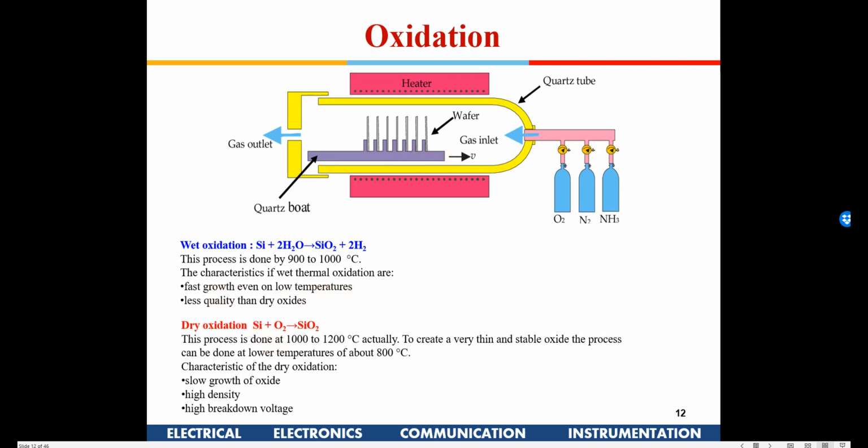See, the oxides will be used like this: we will be putting oxide, removing it, putting it again, for various implant regions. When we are making the oxide just below the gate, there we would prefer dry oxidation. But when we are doing, say, trench isolation, in those cases we can have wet oxidation. So it depends on the purpose, where we are doing the oxidation. It depends on that, what kind of oxidation we do.